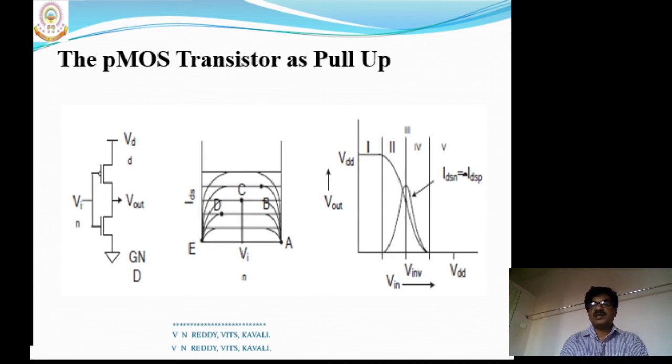You can see in the diagram, this is the current characteristic of this CMOS inverter. The maximum current flow occurs at this time instant, at this input voltage maybe. Only in the transition period, at a particular instant, the power dissipation occurs, which is called short-circuit power dissipation. This is the drawback in this CMOS inverter case.